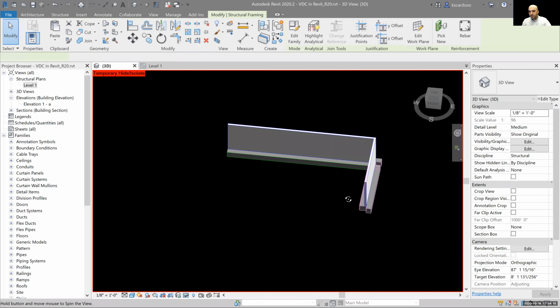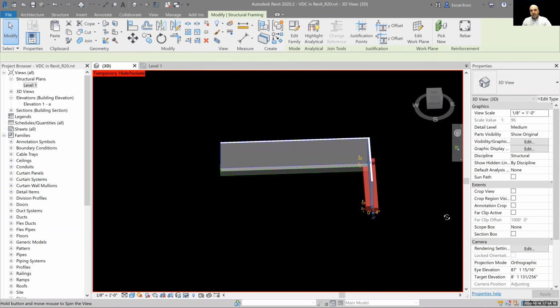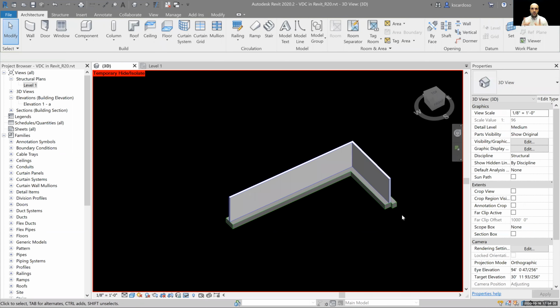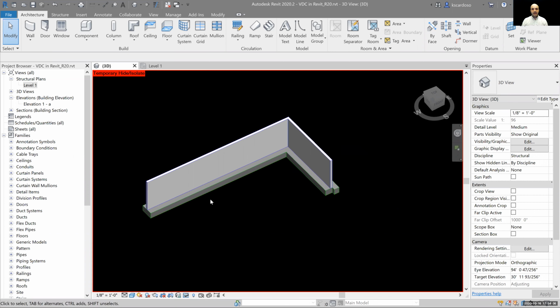All right, and we'll figure out what's going on there. I don't want to add a foundation element once, go to my plan view and align, and then repeat that process. It's best that you go through all of your concrete walls, add your beams or foundation elements before you go through and align them all. Same thing here. If I had a million concrete walls, I'm just placing them at first, knowing that they're not dead center yet, right? And then after, I'll center them all on plan and I'll refine their actual location.